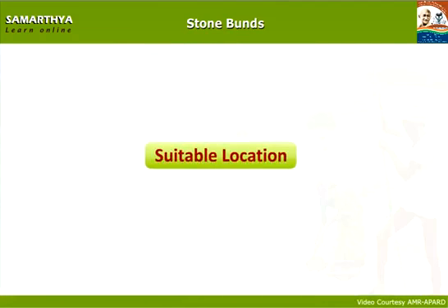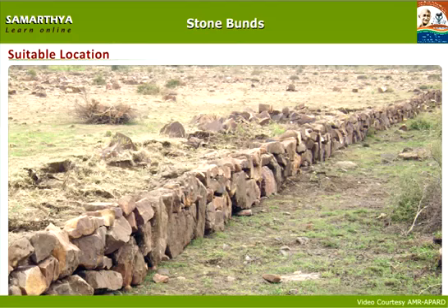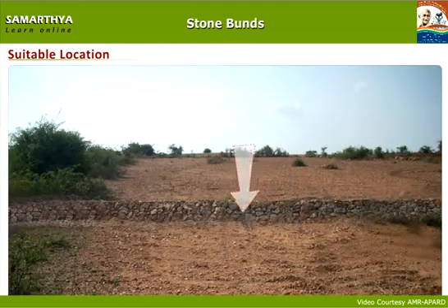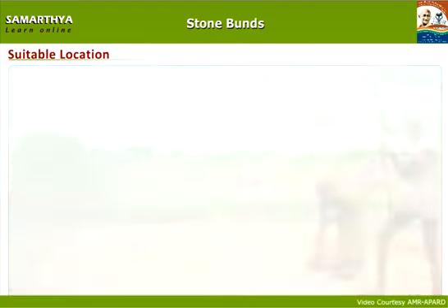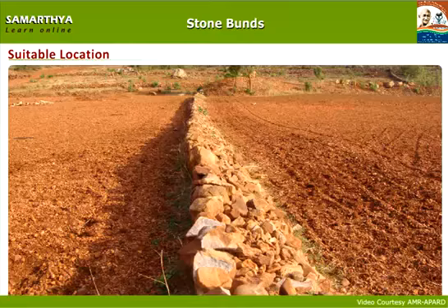Suitable location for construction of stone bunds. Let us see the suitable location for stone bunds. Lands with a slope of more than 6% are most suitable for construction of stone bunds. Lands with more stones and shallow soil depth are suitable for stone bunds.